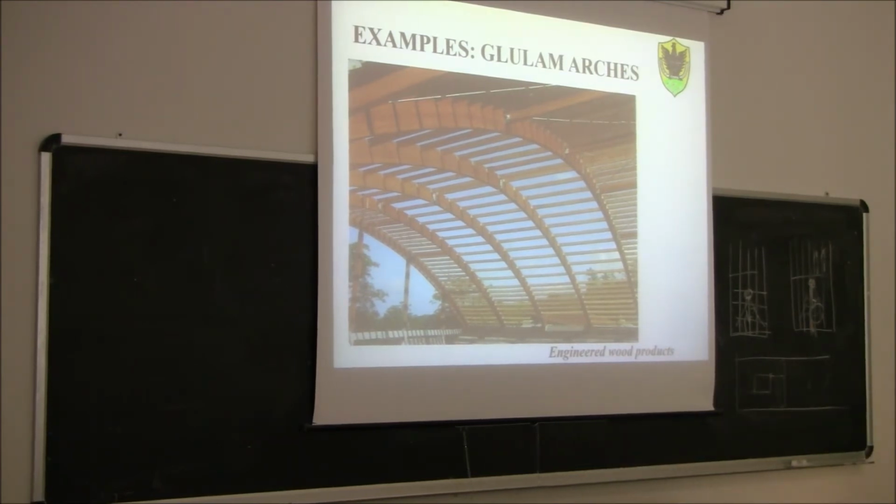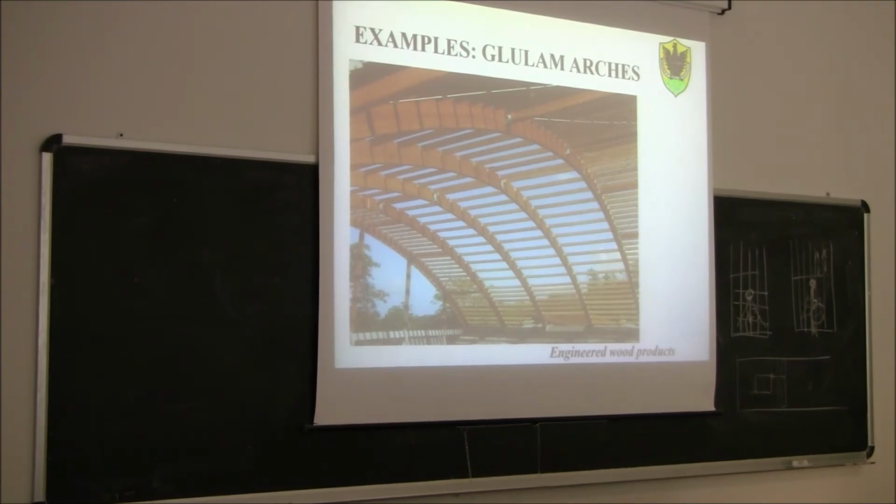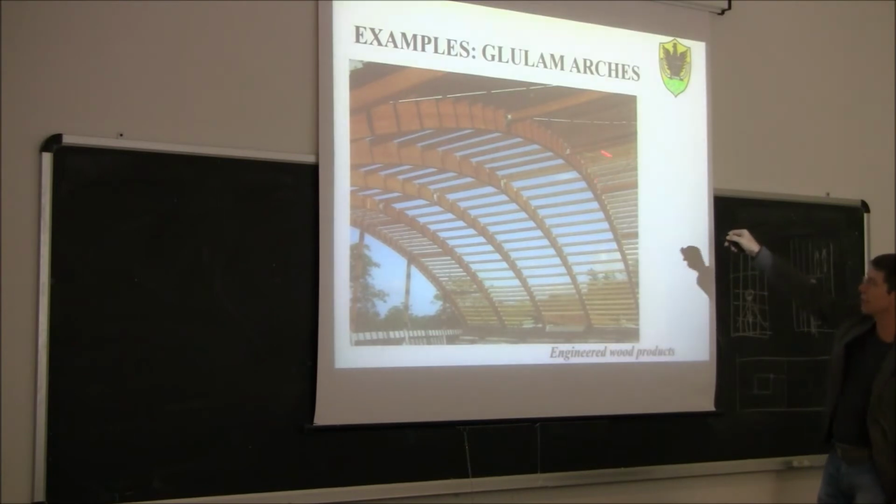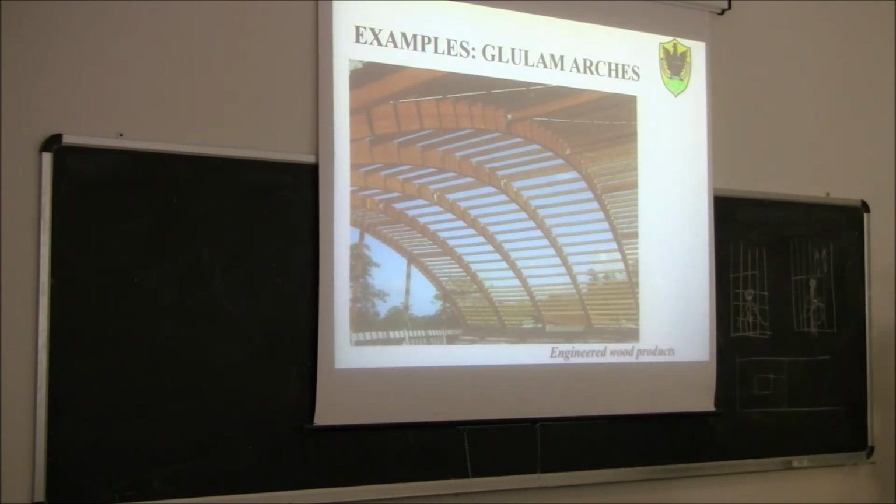Yes, because in this case the designer thought it was a good idea to have a different system for carrying the vertical load, the purlins, and instead to make the bracing. So here there will be a higher purlin to resist the vertical load, and the lower purlin instead to make the bracing system together with the arches and together with the bracings. Okay? It's clear?